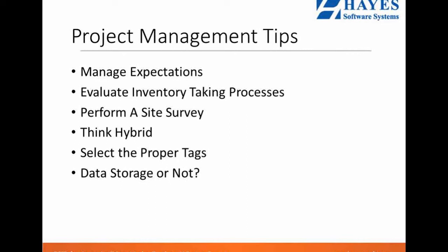When it comes to RFID technology, hybrid often involves utilizing a mix of technologies to create your solution. Utilize print tags with barcodes and human-readable data whenever possible. Not only will the barcode and the human-readable code on your RFID tag be a backup in case the reader or RFID chip fails, but it can also be utilized in parts of the process where an RFID reader does not make sense. This might be a part of the process in which some form of human interaction will still be used, or when you may need to locate or identify a single item among many.